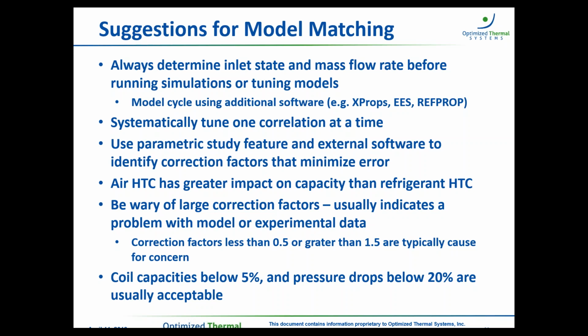We recommend that you systematically tune one correlation at a time. It's very difficult to tune a model with many different correlations varying simultaneously. And so the methodology that we put forward and the flowchart that we've provided should give you a simple approach to tuning a heat exchanger that will be repeatable and that will give you the results that you see in the experiment.